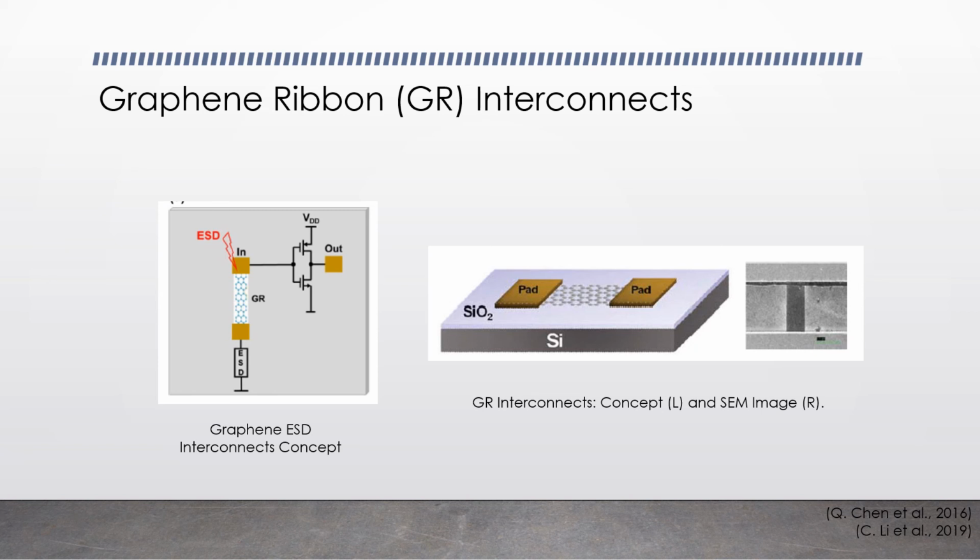If a GR wire is too short and narrow, it may not catch material defects because the current graphene film growth process is far from mature. So it is better to design a long and wide GR, and the GR wires should have dimensions suitable for real-world ICs to ensure useful results.